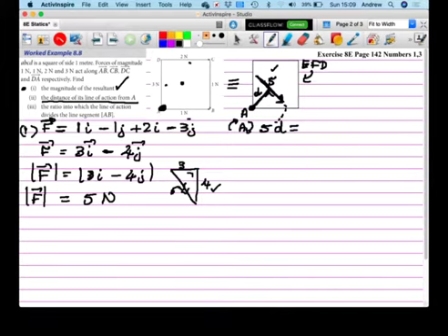Well, the first force I'm looking at is the force of 3 newtons going down. But because this force passes through A, I know this 3 newton force hasn't got any distance from A, so the moment's going to be 3 times 0. I'm now going to go on to this force here, and its line of action goes through A. And because the line of action goes through A, it doesn't have any perpendicular distance, so therefore it's going to be 1 times 0.